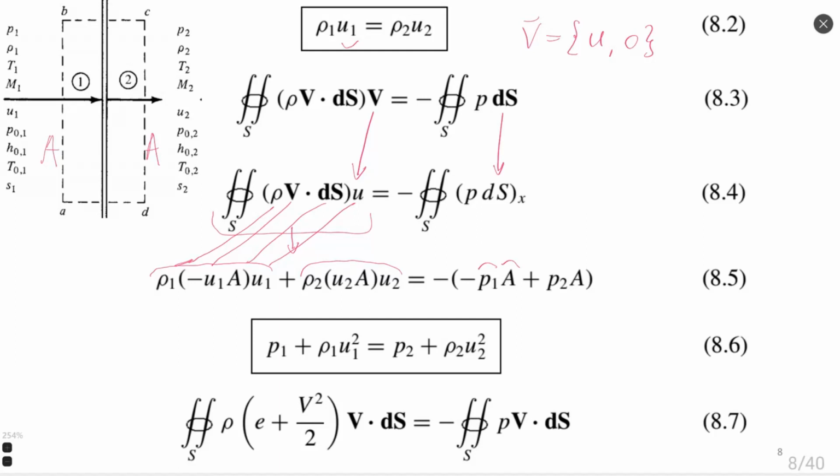component. Even though a shock wave of any type is at least two-dimensional, right? We have x and y coordinates. But since velocity is just going in one direction, we can reduce the problem from a two-dimensional case to just a one-dimensional case. This is possible only in a normal shock wave. In an oblique shock wave, you will see that we will use two equations of momentum in two directions.